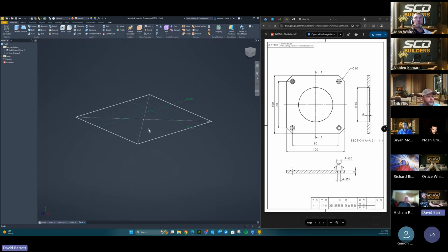So you have your square. And back to that step I was saying, you're going to go back over to this model properties tab on the left-hand side, and choose your sketch. It's going to highlight the whole sketch now. You've got your whole sketch highlighted, and there are some tools that just came up right here.